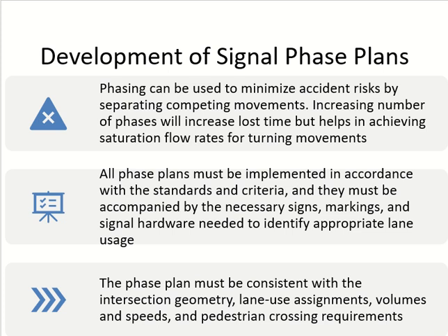So the next point I was making is other control devices you have to use at the intersection according to your phasing plan. So for example, you decide I will provide one phase for straight and a separate phase for left turning. So there are two phases, one for only straight, the other one for only left turning. Now with this phasing plan, what are the things I have to do at the intersection to make these two phases happen at different times?